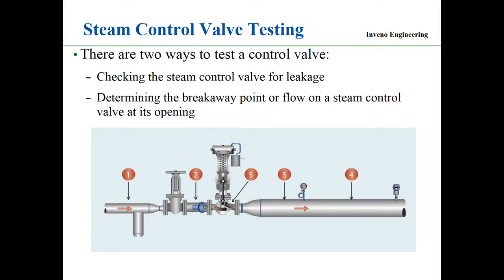It's very interesting when setting up a control valve, sitting there with a 4 to 20 milliamp generator and seeing exactly what point steam starts to pass through the valve. Because I'm trying to set up a PID loop. And the PID loop assumes 4.0 milliamp is 0, no flow, and 4.4 milliamp, there is flow. If I have a dead band down here on the PID loop, the valve doesn't start to pass steam until 5 or 4.8 milliamps. It does start to cause some issues with the PID loop setting it up and tuning it.